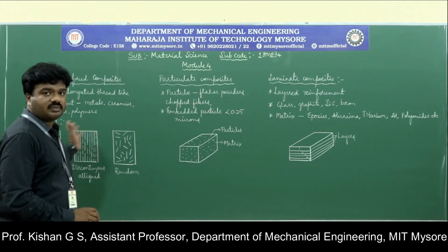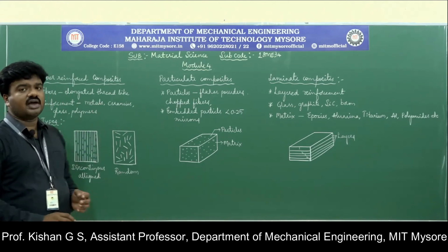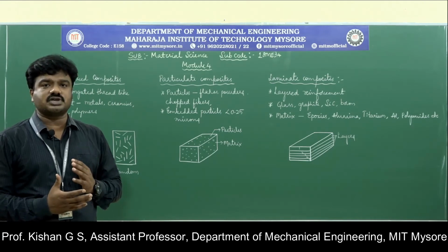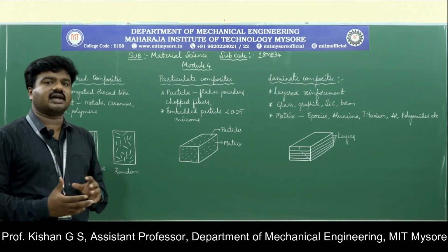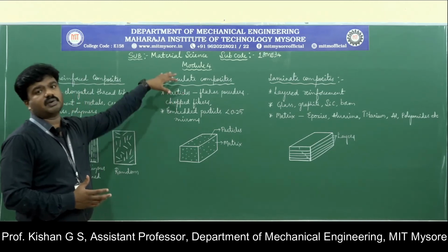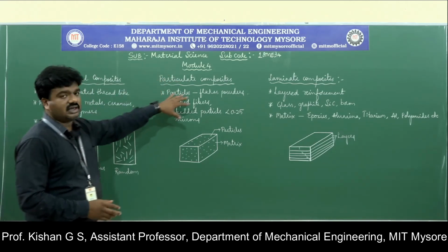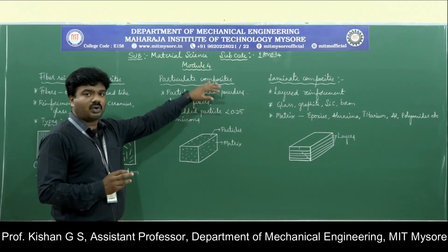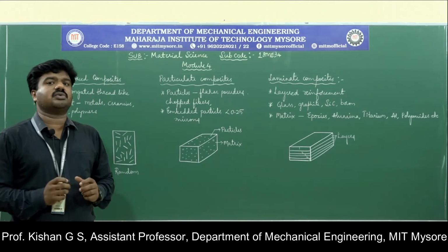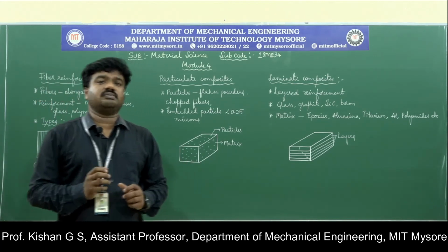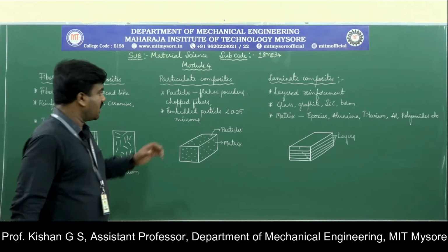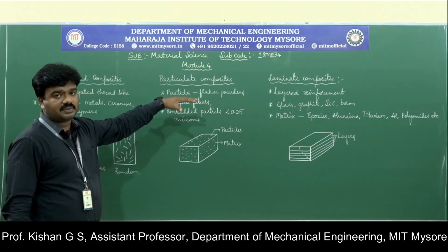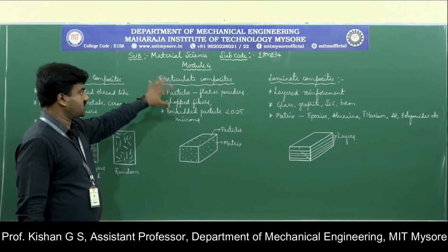So if you take the fibrous composite or fiber reinforcement, the elongated, thread-like structure, if it is cut into pieces of a very small size, even that can be considered as particulate in the particulate composite. So basically the reinforcement type will be flakes or chips in nature, small chips, powdered. Powdered may be completely amorphous or may be minimally crystalline in its nature, as well as the chopped fibers.